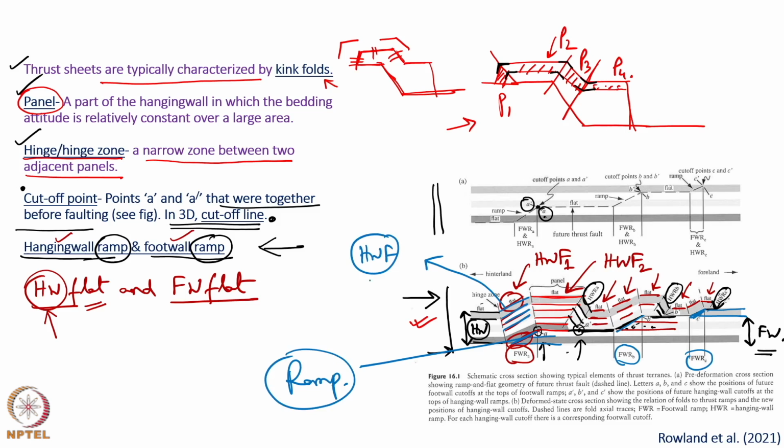On the fault ramp, hanging wall flat is lying, and in this place what has happened, the fault plane is flat and there the hanging wall flat is defined. So, we can write on ramp, that means a ramp geometry fault plane, we can have hanging wall flat. Similarly, we can explore the term foot wall flat.